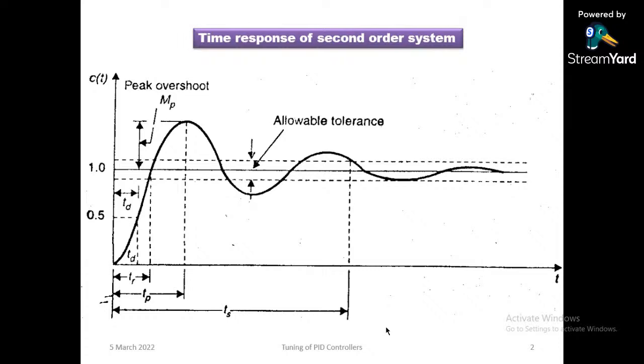And if you want to improve both at a time, that is transient as well as steady state, you can go with a lag-lead compensator, right? Now lag-lead compensator means what? Lag or lead means what? Just adding one simple pole and one simple zero into the system. Whether the pole is dominating or the zero, based on that we have categorized whether it is a lag or lead compensator. Okay. Now instead of that compensator, we are going to use a controller.